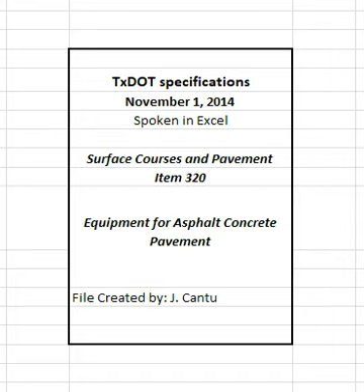2.1.1.8 Truck scales. Provide standard platform scales at an approved location. 2.1.2 Weigh batch plants. Provide a mixing plant that complies with Section 320.2.1.1, drum mix plants, except as required below. 2.1.2.1 Screening and proportioning. Provide enough hot bins to separate the aggregate and to control proportioning of the mixture type specified. Supply bins that discard excessive and oversized material through overflow chutes. Provide safe access for inspectors to obtain samples from the hot bins.